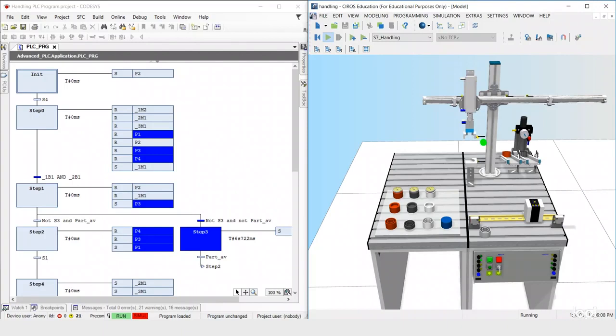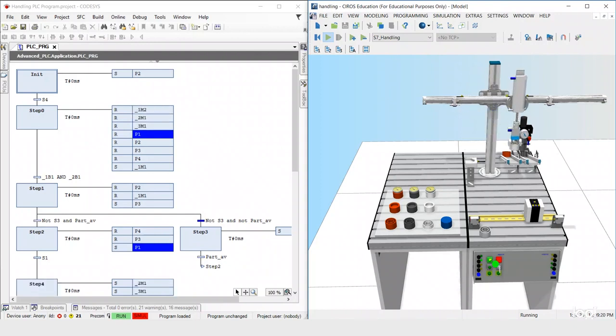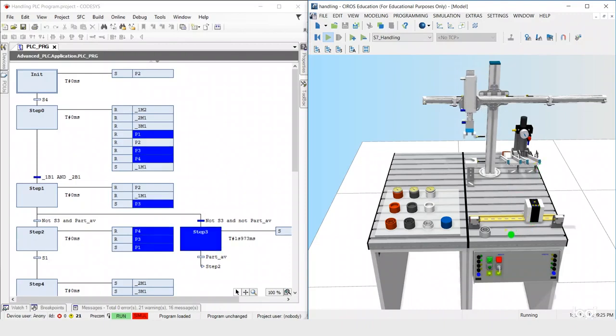So it uses an optical sensor here, which is tuned so that it detects bright objects such as the red and any other brighter object. So if I select silver, you will see that it will regard it as a bright object and sort it into the first slide. Any object that is black or darker than black will then be sorted into the second slide. Or this sensor can be adjusted so that it regards red as a dark object and sorts it into the second slide, and then silver, which is brighter than red, into the first slide. So this is something that can be customized.